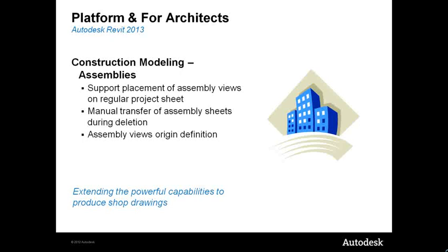Each assembly now has an origin, which is visible and editable in the Edit Assembly mode. The origin determines the default orientation of assembly views, and you can now rotate assembly views to better orient them to produce more organized shop drawings.